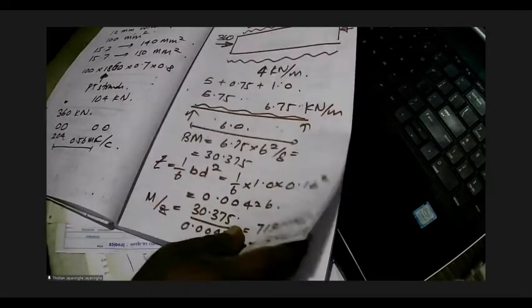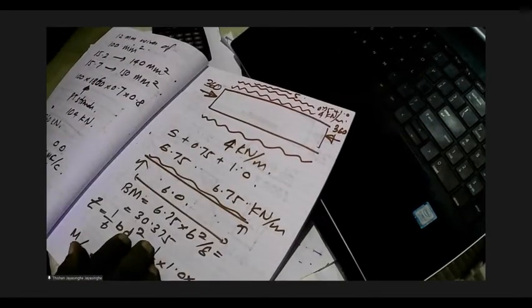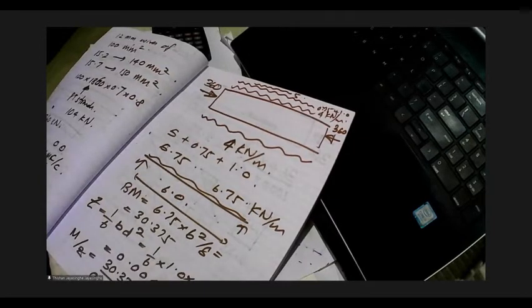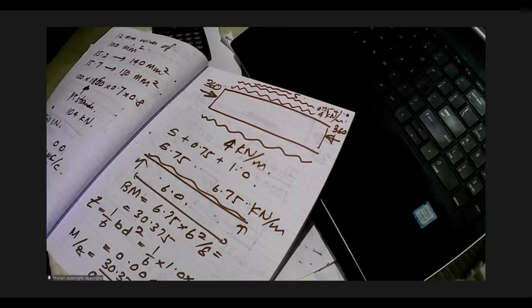So here I have again used this load balancing method, and I have balanced the dead weight of the structure. And you can again see I have used a thin slab, 160 millimeters. So what are the advantages of this? Under normal situation, we consider that the slab is not cracked. If the slab is not cracked, the second moment of area is high. And if the second moment of area is high, deflection will be low.